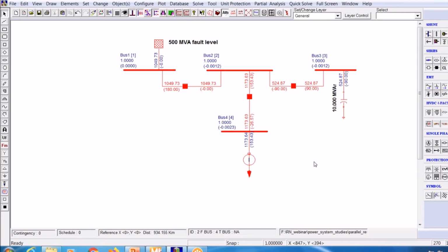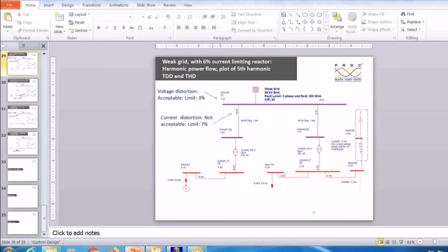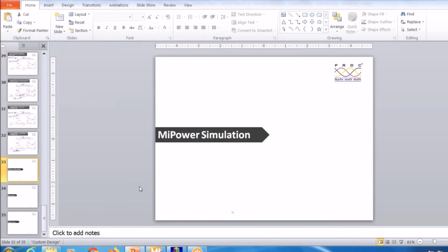harmonic voltage will increase. Therefore, in the harmonic study, it is also important for us to understand when the series resonance will happen and when the parallel resonance will happen, and based upon that, our software has all the facilities to understand the various conditions like the series resonance and also the parallel resonance conditions.